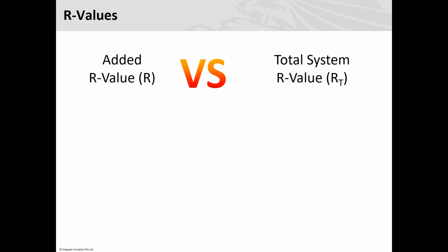So thanks, Mike. That's so right. Just on those, basically those walls, roofs, and if it's an elevated floor, a suspended floor, that will need to achieve an R value as well. Now the R values that Mike's talking about are total R values, and that's what the National Construction Code will ask for, total R values.